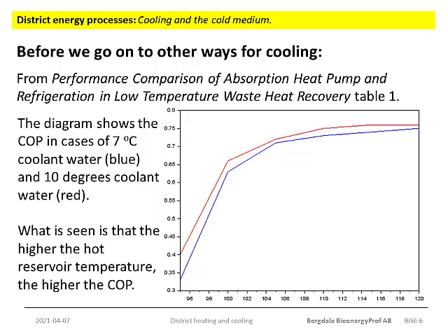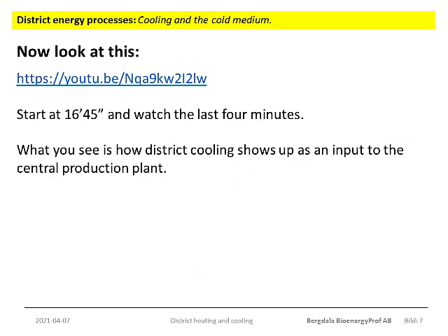And at a COP of 0.33, we'd have to supply 3 megajoules. But then we would be able to produce more electricity. So we will have to compromise. But the absorption heat pumps give a system with a fair amount of flexibility.